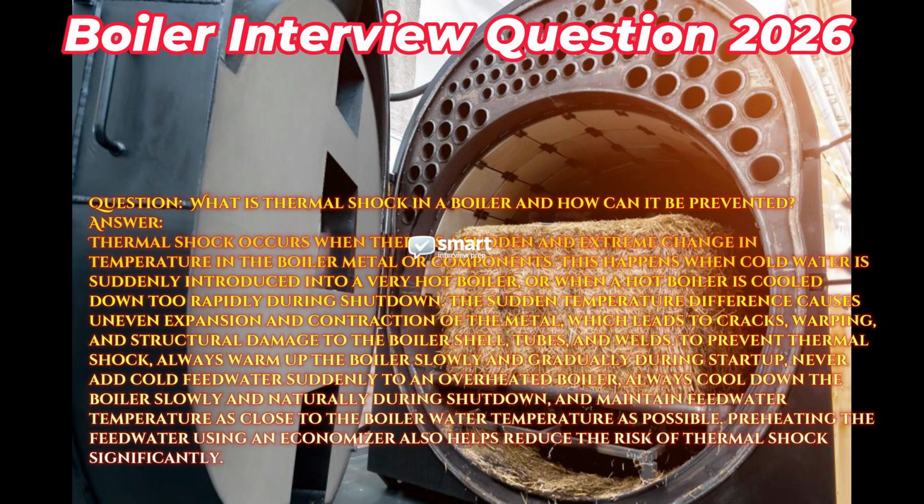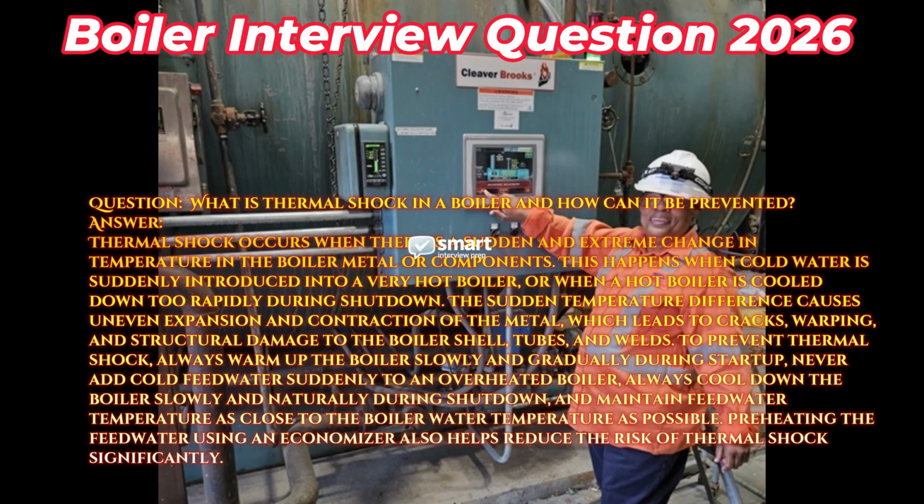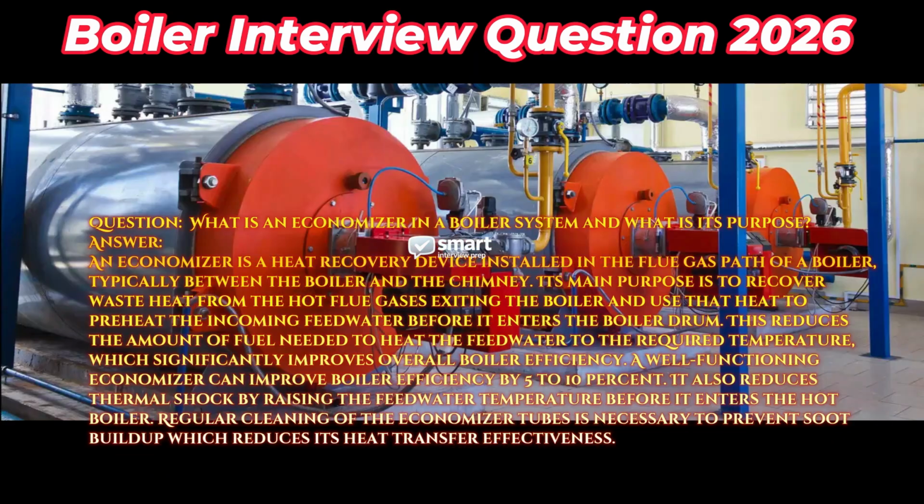Always cool down the boiler slowly and naturally during shutdown, and maintain feedwater temperature as close to the boiler water temperature as possible. Preheating the feedwater using an economizer also helps reduce the risk of thermal shock significantly. Question: what is an economizer in a boiler system and what is its purpose?